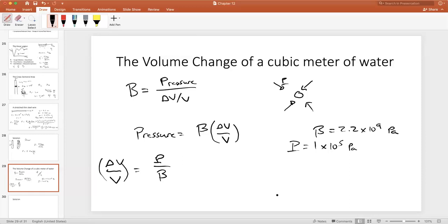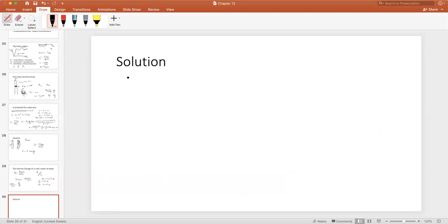It's actually 1.01. I'm going to use 1. So at sea level, how much is the fractional volume change versus in a vacuum? And then the pressure at the bottom of the ocean is, we assume 4 times 10 to the 7th pascals. These are actual numbers, just so you know. So let's solve them. Let's find out what the fractional volume change is of water at the bottom of the ocean and at the surface of the Earth.